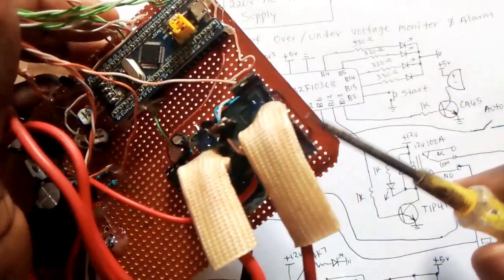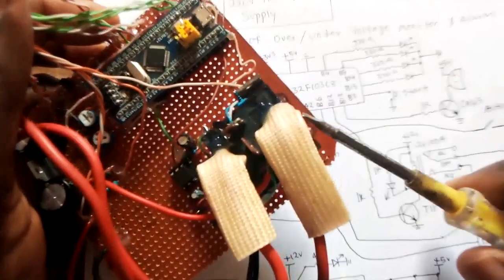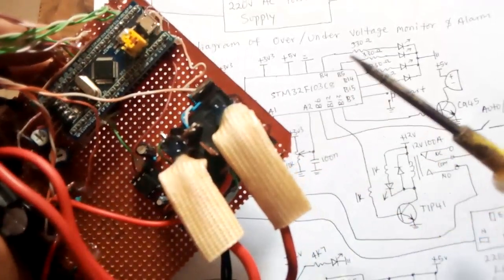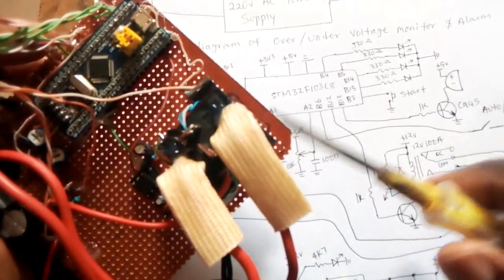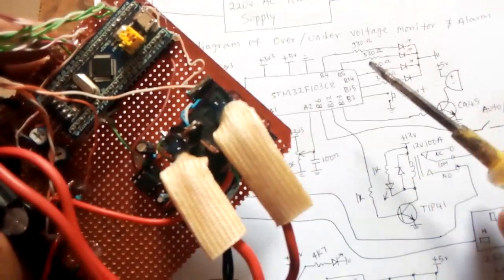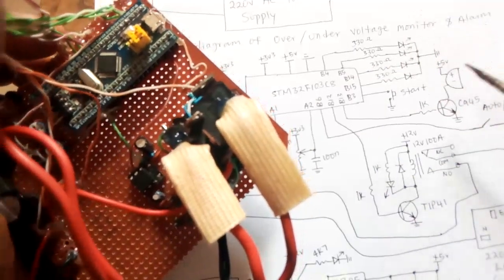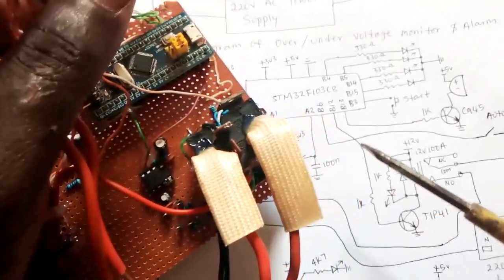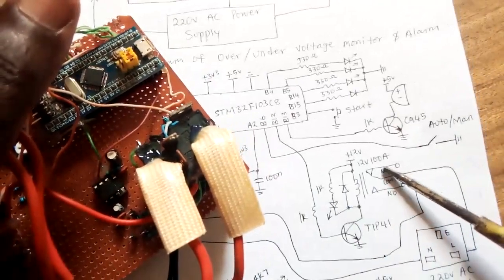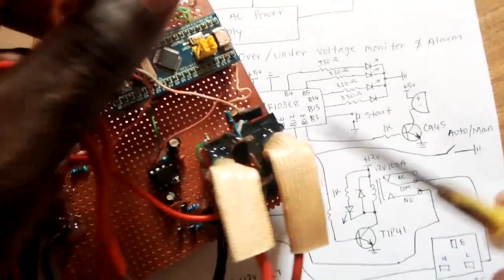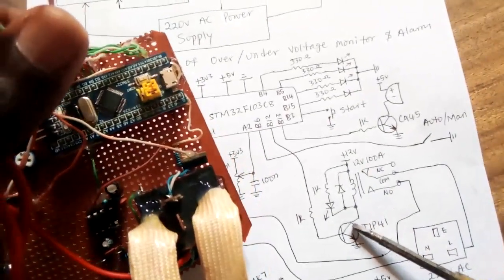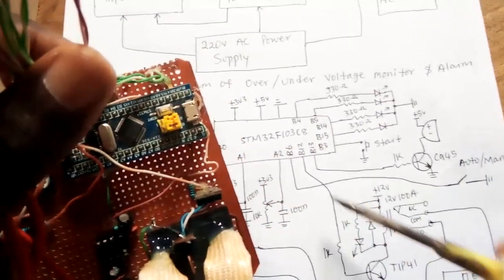Now if you want to power the whole of your house with this system, you can't use this relay directly. You're going to use contactors. This relay is going to drive those heavy contactors, so the contactors will be the ones that drive your load. But in this case, just for my electronics, this 100 amp relay is okay. And then the relay is driven by a transistor here, with control received from the microcontroller.